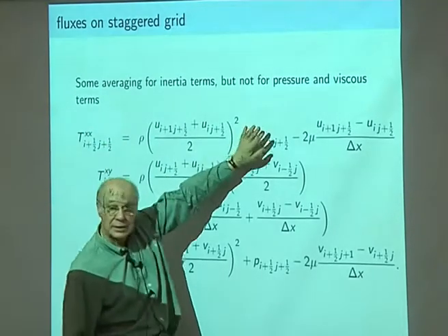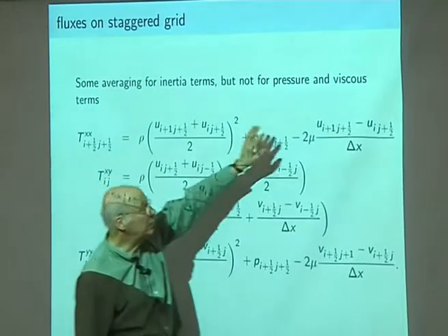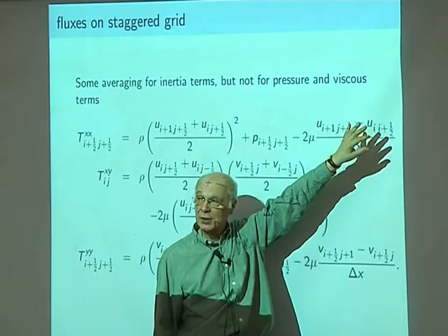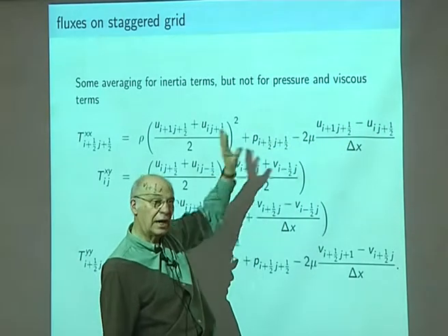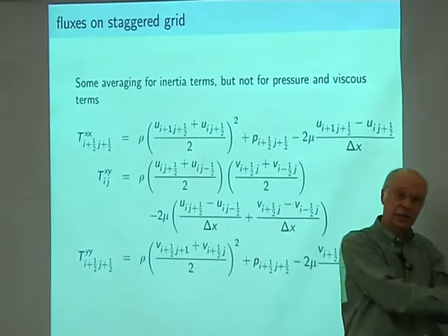The pressures are exactly in the right place, so the pressure occurs very simply, and equally the viscous stresses, they are simple differences. But getting the Reynolds stresses, I have to average the velocities from where they are to where I'd like to work out the stress.